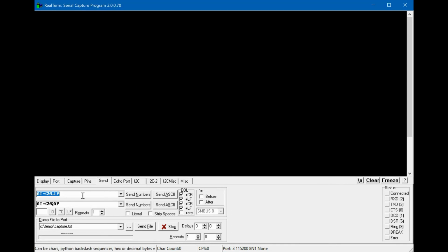And finally, the last mode, let's switch ESP8266 to the dual mode. Now, ESP8266 acts as an access point and connects at the same time to the existing wireless network. To fully customize parameters of both connections, we may use the same commands we used in previous examples.